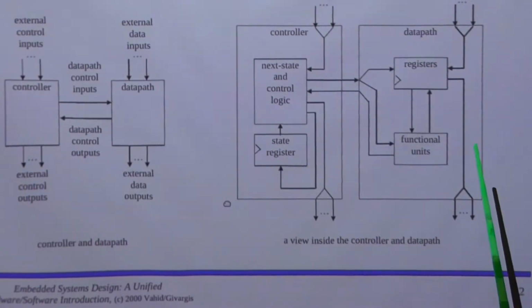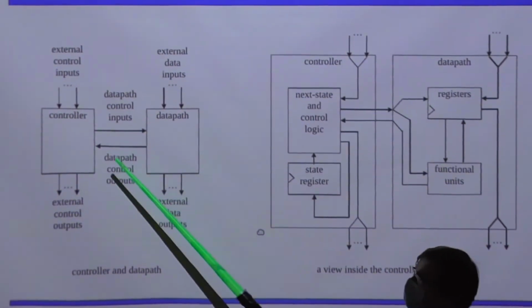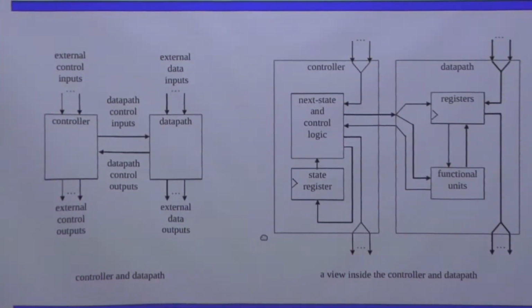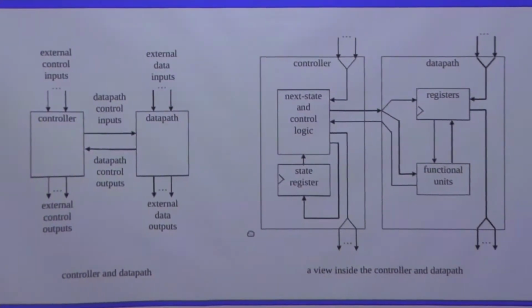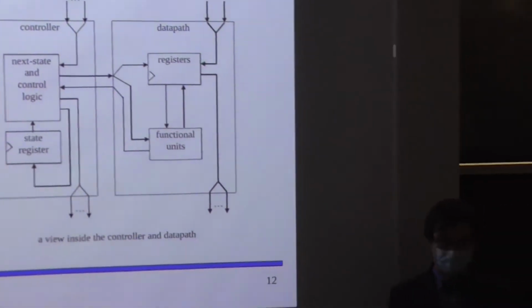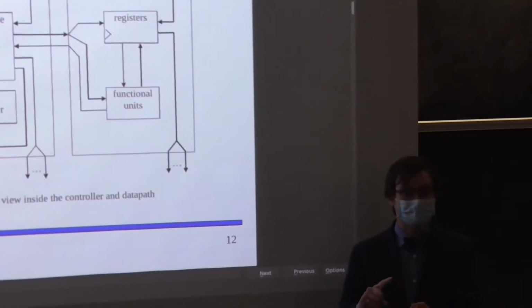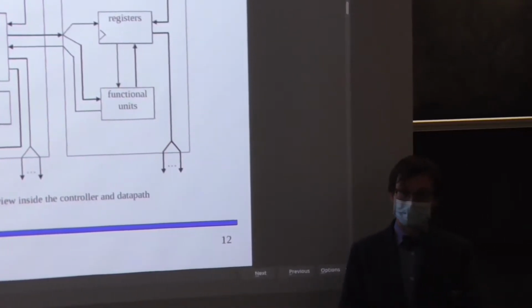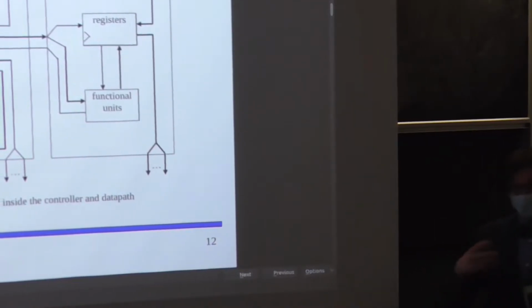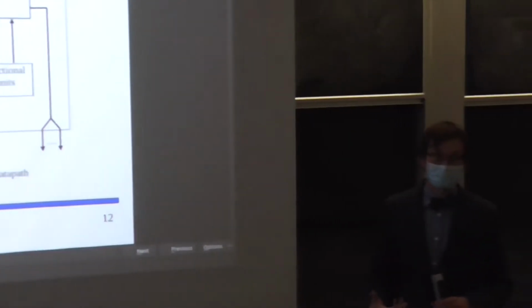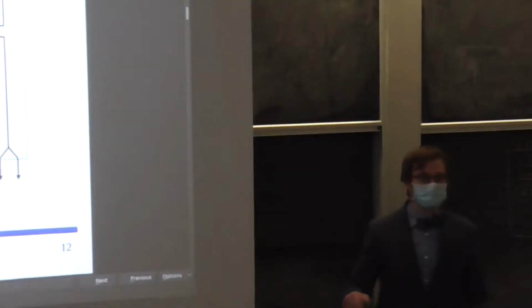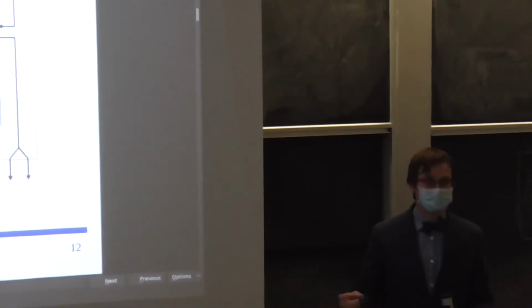So the question becomes, how does the controller actually control what's going on inside of the ALU? Well, I kind of hinted at it earlier. It's controlling such things as the selector signal on multiplexers, and it's controlling such things as the load and clear operations on registers, right? So all of these operations need to be coordinated, right? In the previous example, we just assumed that values were being stored automatically, like once every clock cycle, right?